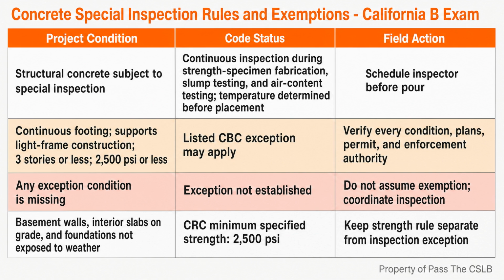This is a testable concept based on the CSLB study guide because it combines concrete, field inspection performance, coordination, and code compliance. The useful study habit is to ask 2 questions. Does this concrete fall under a special inspection requirement? If an exception is claimed, do all conditions of that exception actually match the project?